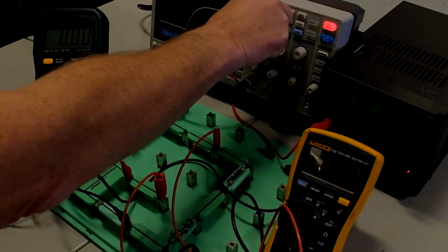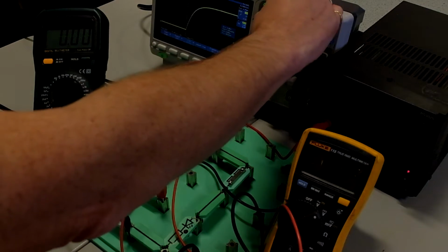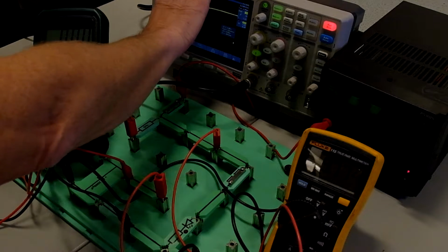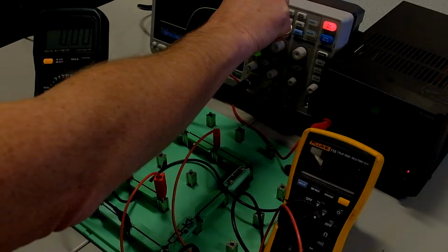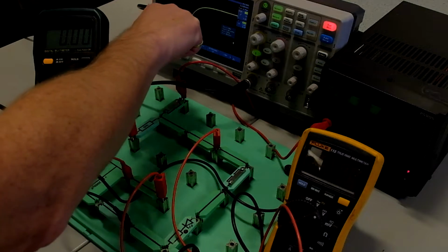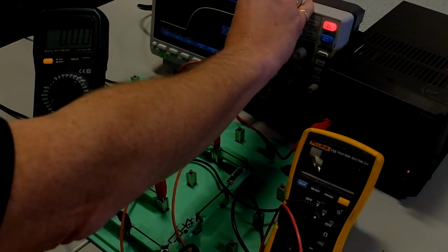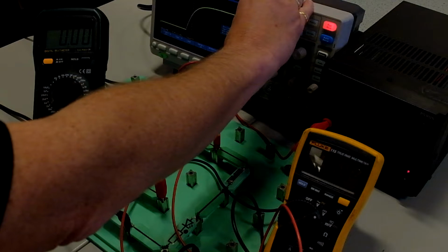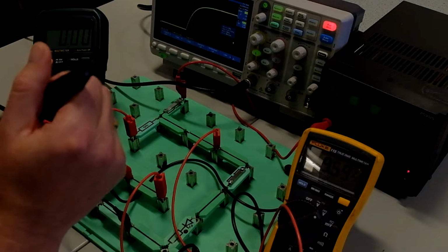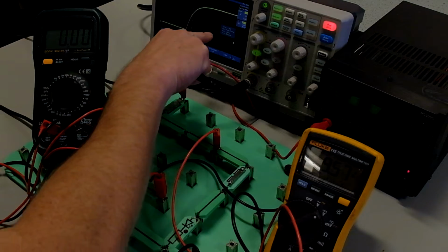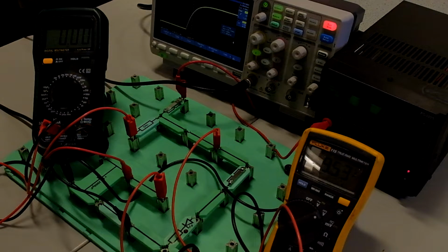So I'm going to put that cursor there, which is time 0, 0 volts. I want the other cursor, so press cursors. I want to measure it so I can move it. What we're looking for here is 6.3 volts. We're on 2 volts per division vertically, so 2, 4, 6, just above here. So if we go to here, just the other side, for 6.3 volts. We're on 0 volts here, 2, 4, 6, just above 6 is there. And if we measure, we've got 2.12 seconds. So within reason, that does verify our mathematical expression.